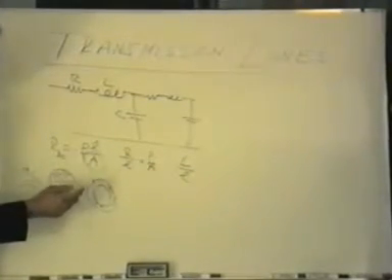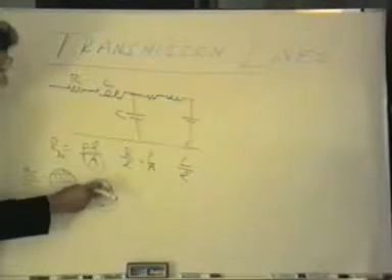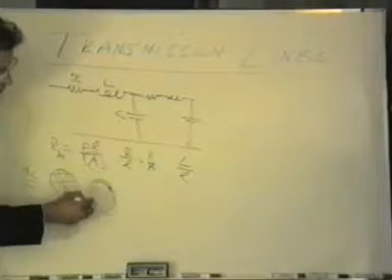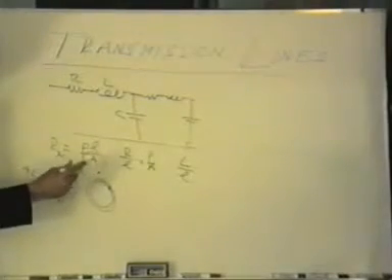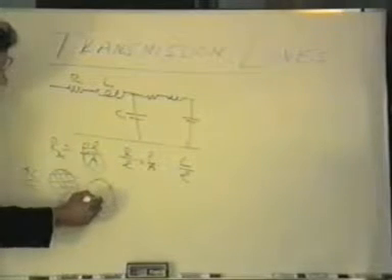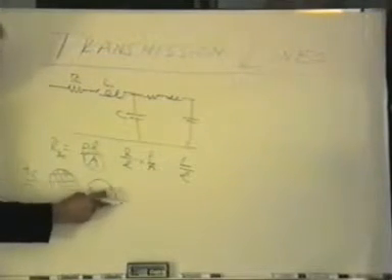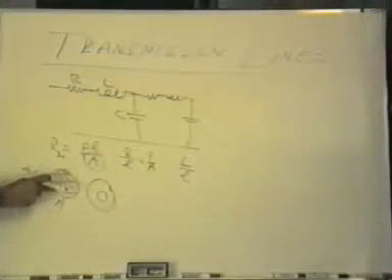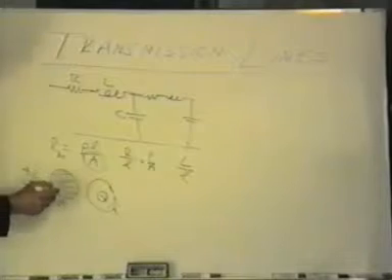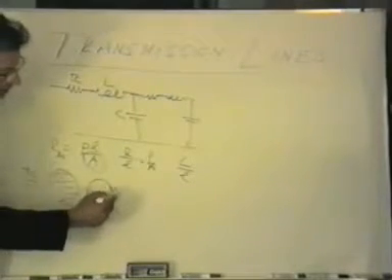The higher the frequency of the signal, the thinner this ring becomes and starts moving out more towards the edge. As the frequency starts to drop, the ring starts to move in towards the center, and eventually as you approach DC, it comes back to this picture. This distance between these two rings where the conduction is actually occurring is called the skin depth.